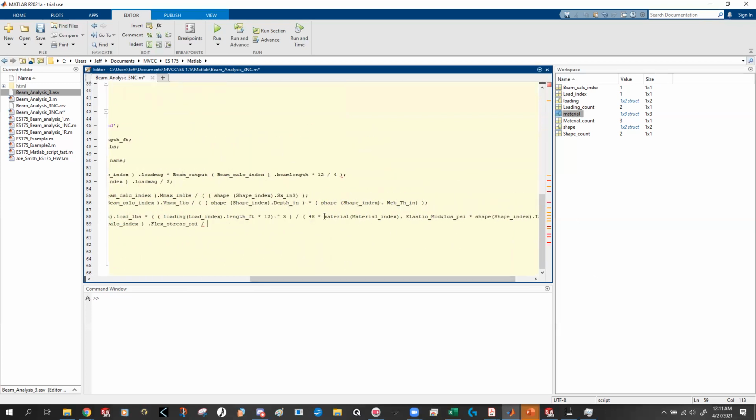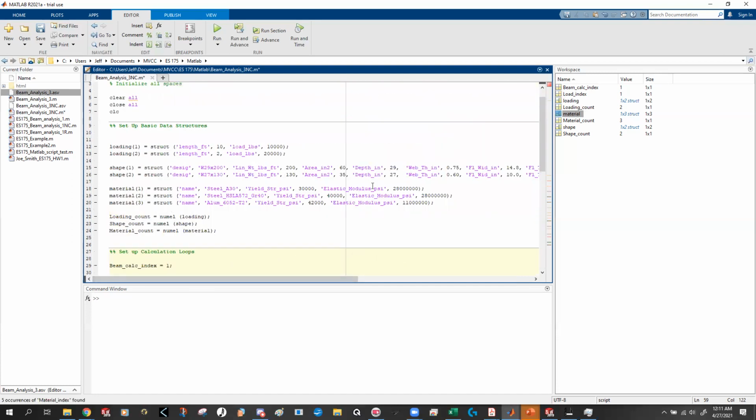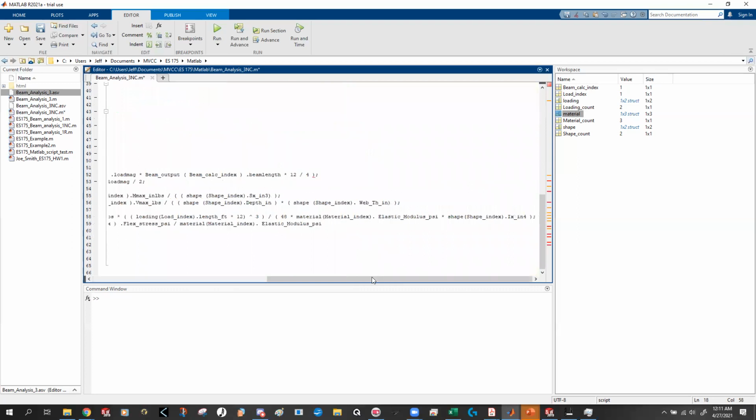So if I can copy that. Okay, so yield strength, where'd you go? Here. Okay, so we divided the stress that we have by the yield strength of the material. So once we get to the material's point, then we know that it's going to start breaking, and that's bad. So we want this well under 1.00 if possible.